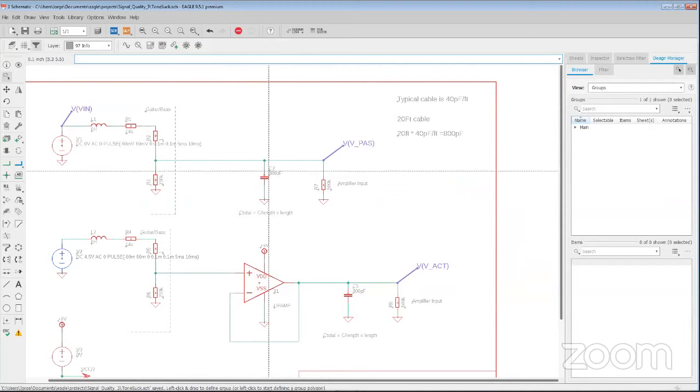So this value is getting higher and higher, and it's going to start to interact with your instrument's internal electronics. Typically what will happen is that you'll get high-end roll-off. You'll lose clarity. And that's colloquially known as tone suck.